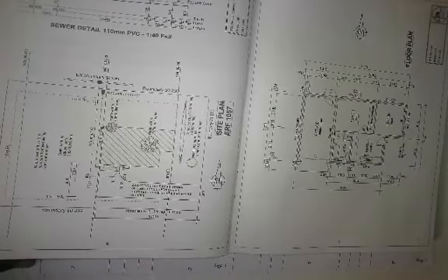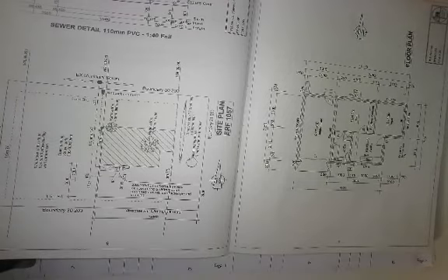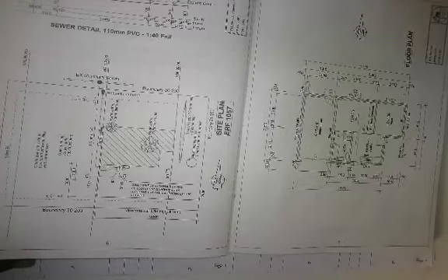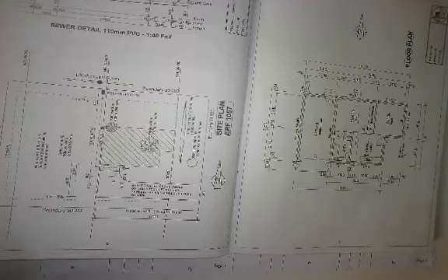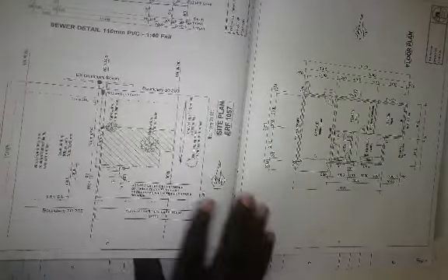For instance, if you come to this site plan, already you can see you've got a hedge, some trees, a big tree there, a small tree there. All of these need to be removed, right? These are the things you need to note. They can also just say to you, just clear around the footprint of the proposed house. So basically, you just need to allow for working space around the footprint of your house. Okay, guys.